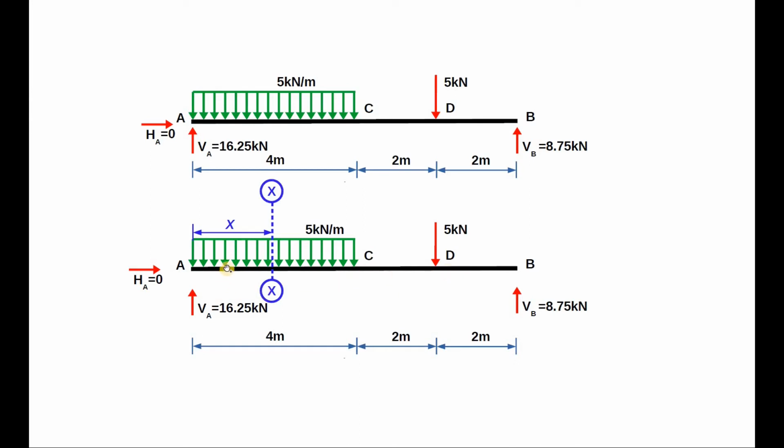We will generate the mathematical expression for both shear force and bending moment, and then we will calculate the values at each critical point. We'll join the values by the curves represented by mathematical expressions generated within each segment.